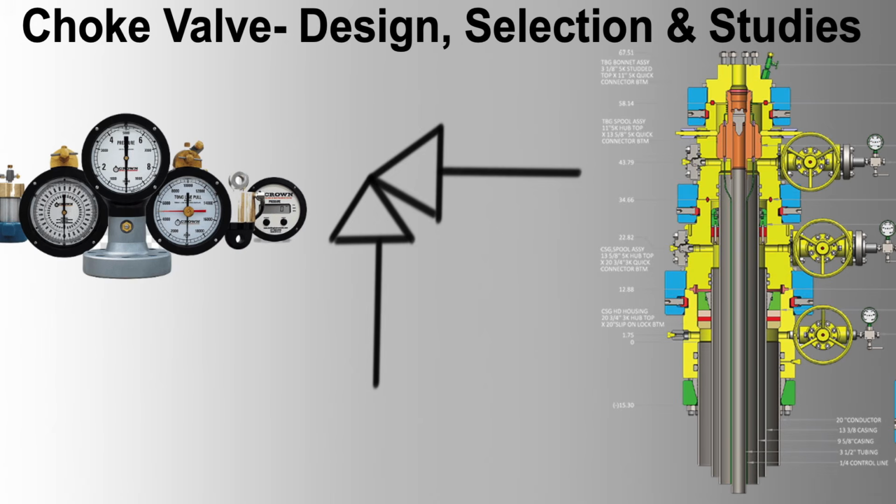Construction. 1. Body. Design: robust and capable of withstanding high pressure and temperature conditions. Materials: select based on the fluid characteristics, corrosiveness, and erosiveness. Common materials include stainless steel, carbon steel, Inconel, and Hastelloy. Pressure rating: ensure the body can handle the maximum operating pressure and potential pressure surges.